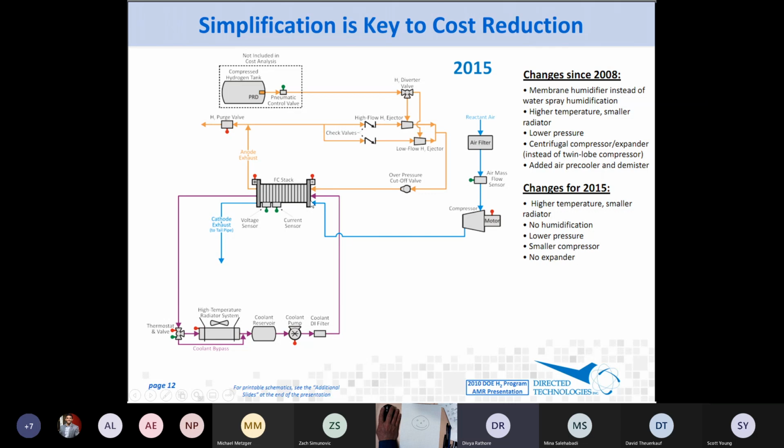The water which we produce is used to humidify the membrane, maybe. I guess that must be the case, but you know, if we try to run a fuel cell without any humidification, I can tell you lambda is going to go to 0 at the anode side with the fuel cell that we were using before.